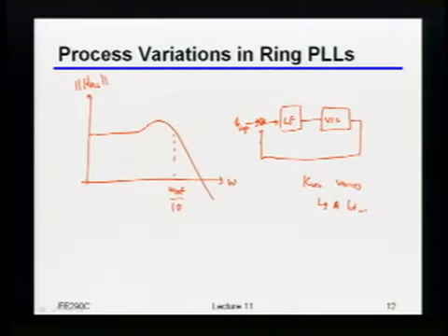If I increase the KVCO, that's like saying I've increased the forward gain, so from an open loop standpoint, I'm pushing out the crossover. And if I've got some third order pole or just my sampling frequency sitting there creating some large phase delay, if I increase that KVCO, guess what? This thing will just go off to infinity, and you'll be unhappy and nothing will really work.